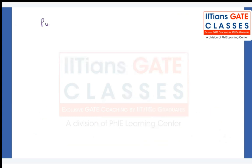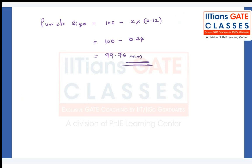Punch size is equal to this. We have solved so many questions, guys. So blank size 100 minus 2 into 0.12, such that it is going to be 100 minus 0.24. So now here I can write it is 99.76 mm. This is your punch size. Okay, right. Now hope you understand, guys.